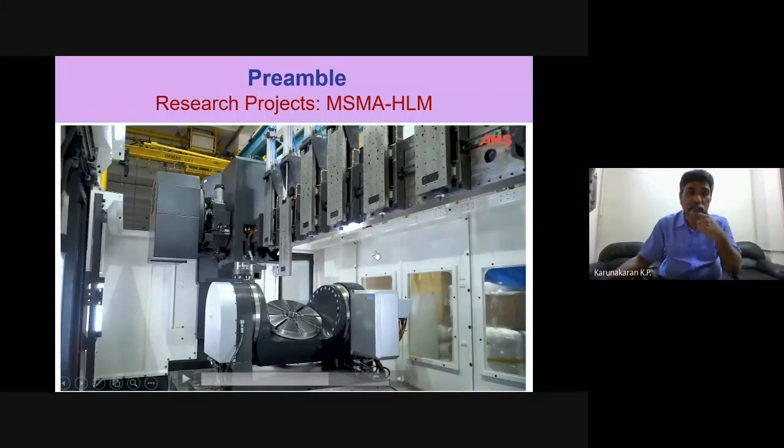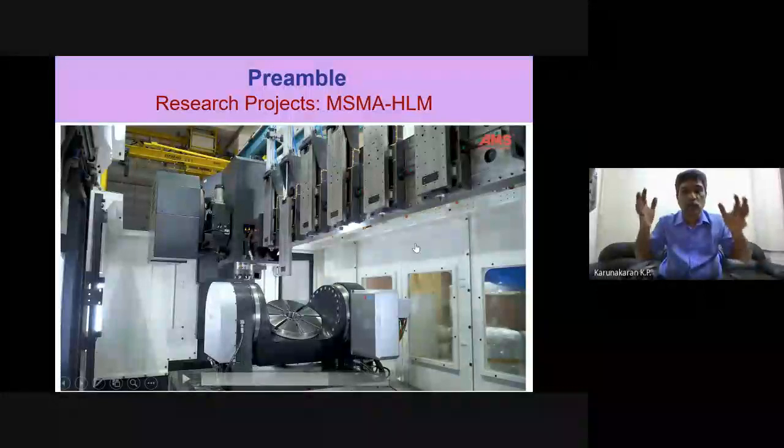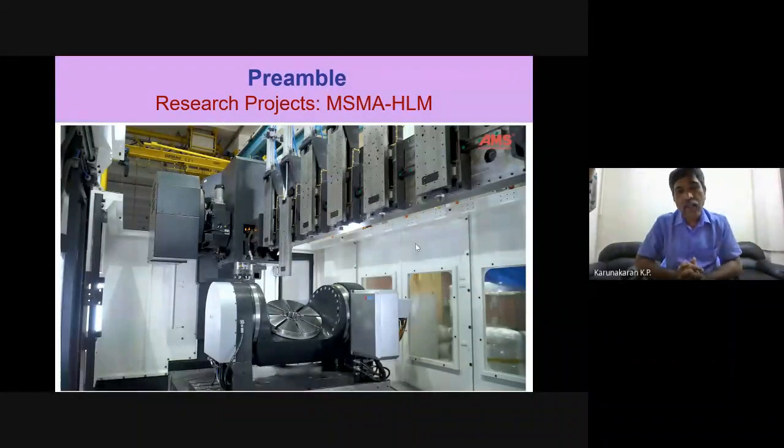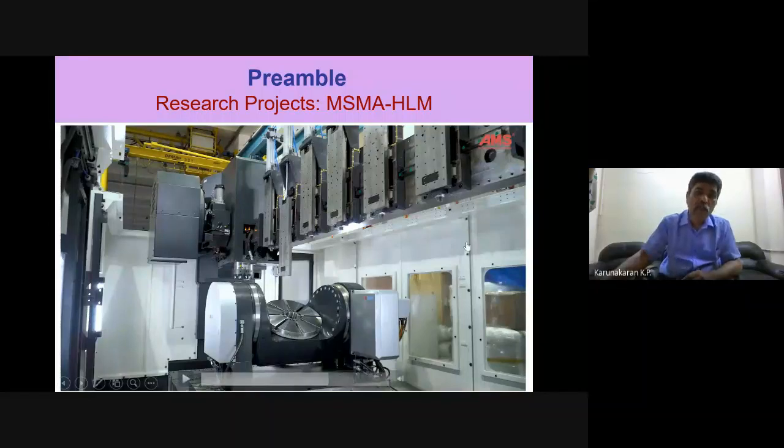And additive manufacturing is a unique process where we suffer extremely high aspect ratio. Unlike machining, where you start with the bulk of raw material, here you put the raw material in a layer by layer manner. That means the aspect ratio, which is the dimension in X or Y over the thickness, can become as much as 2,000 to 20,000 times. So it becomes a big problem. It leads to warpage, and in worst cases like hard materials, it results in cracks also.